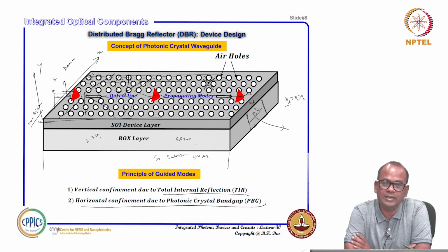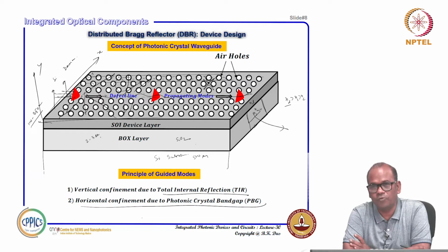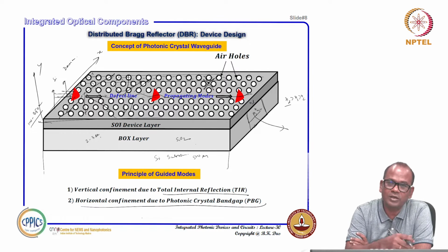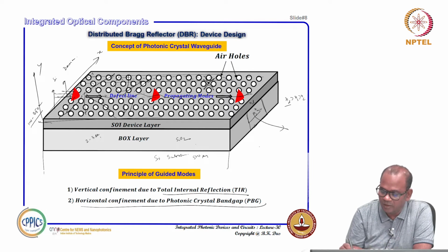One advantage here is that in the photonic crystal, as we will show later, any mode guided through this defect line, or even in the DBR structure in transmission, will have a very large group index, Ng, much higher than in the normal strip or photonic wire waveguide structure.